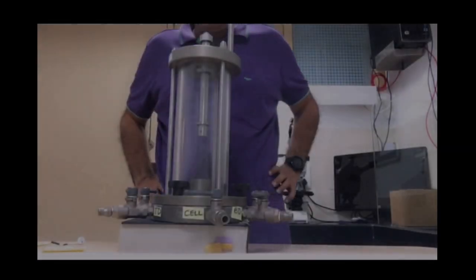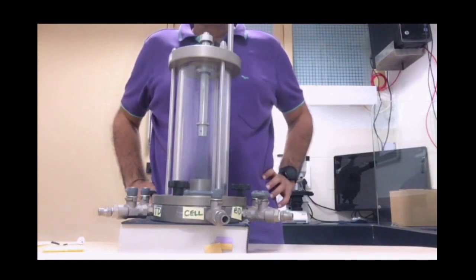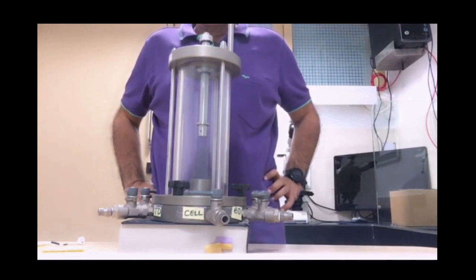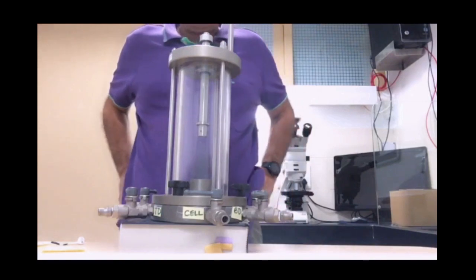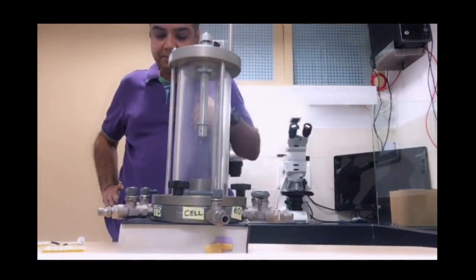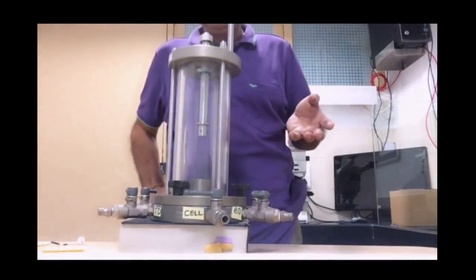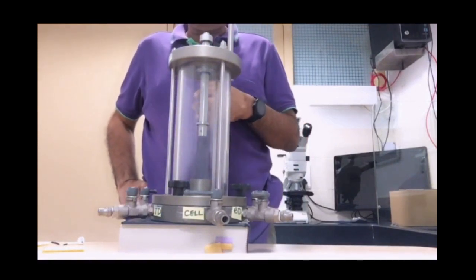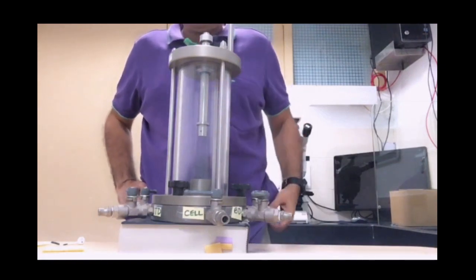So the three tests which we just discussed are only feasible if your sample is saturated. The important point in triaxial testing is you need to use a saturated sample. In cases where your sample has come up from the ground, even if you have collected a sample from below the water table, when it comes above the ground and is transported to the lab, a certain amount of loss in water is expected, so the degree of saturation can go down.